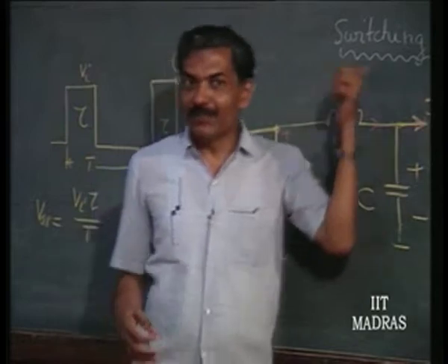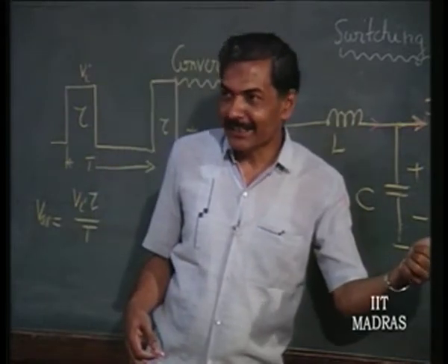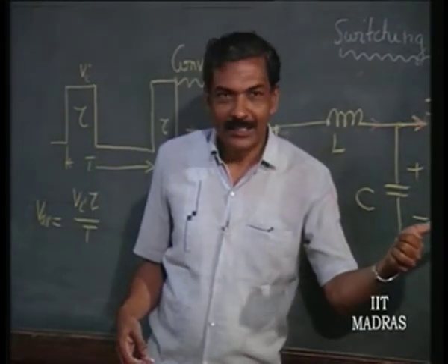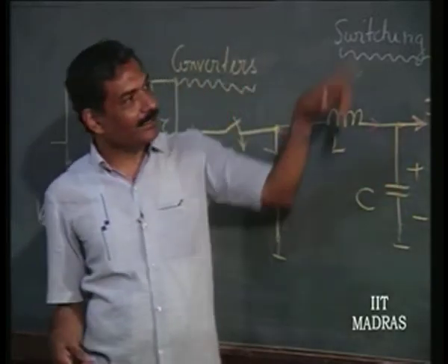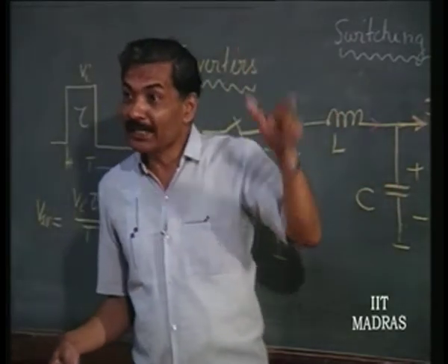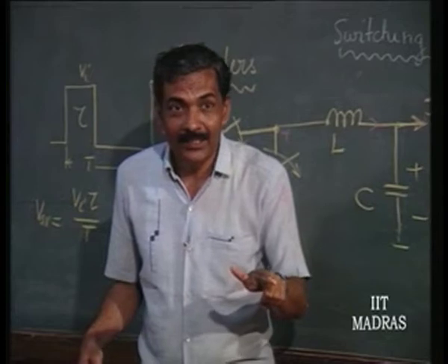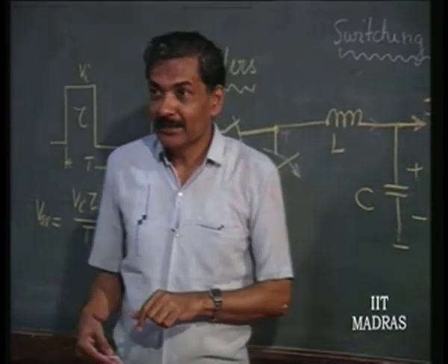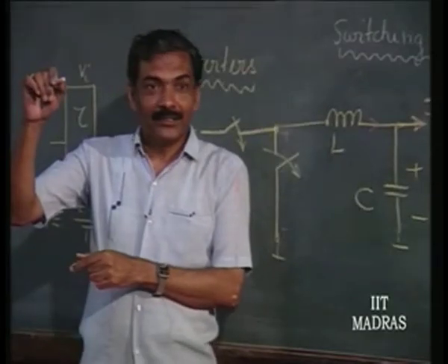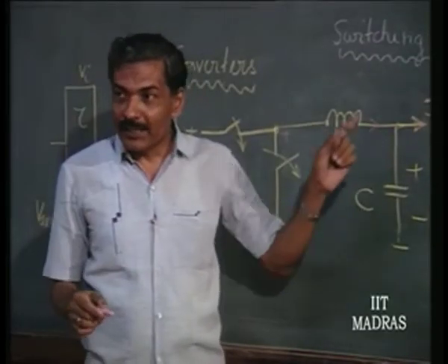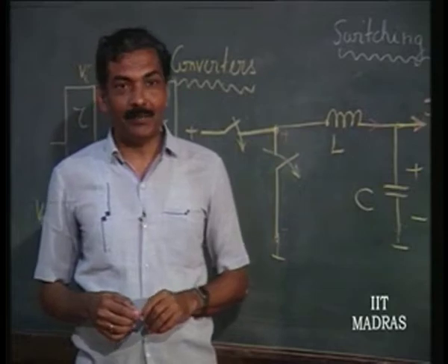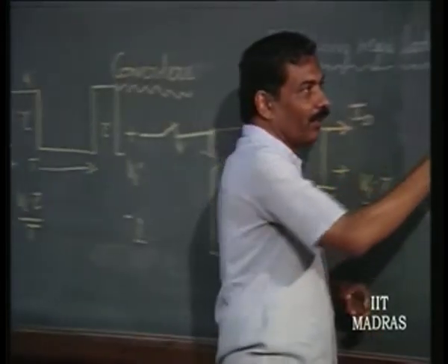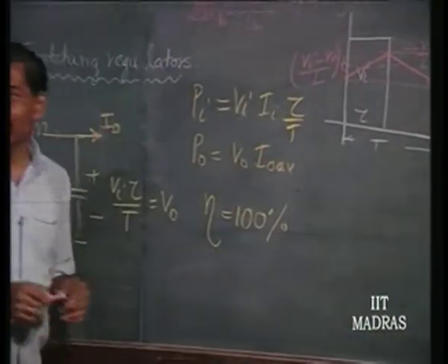The DC current will flow into the resistor, you have to assume obviously, and the AC current, that change in current, will flow entirely, if you have done a good design, into the capacitor and develop a voltage dependent upon what the current is. How do you find out the voltage across the capacitor? You know the current waveform, triangular.